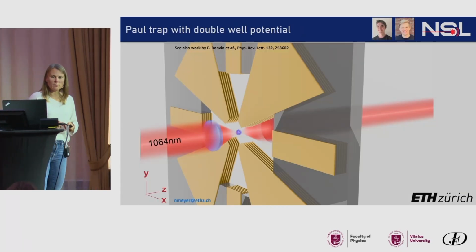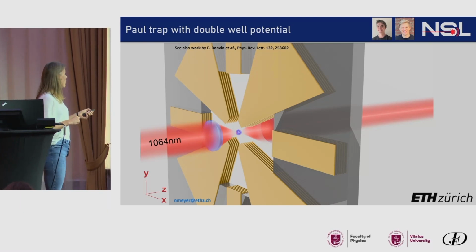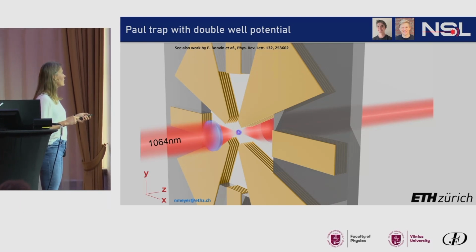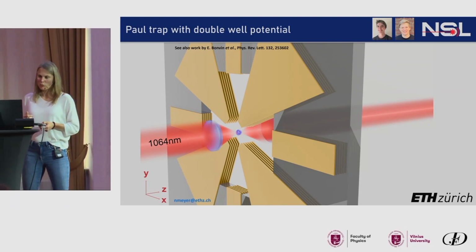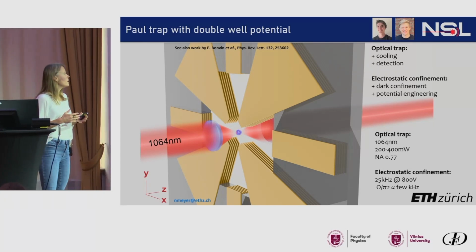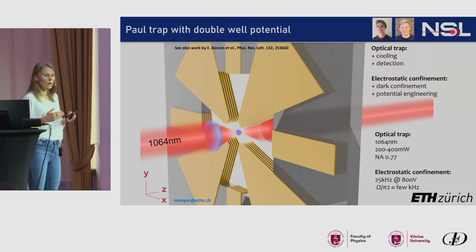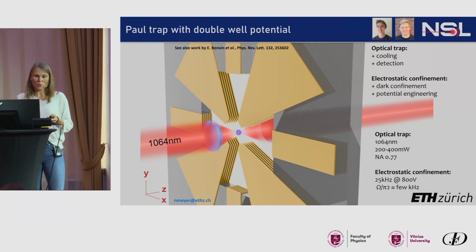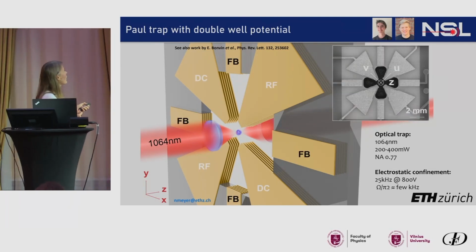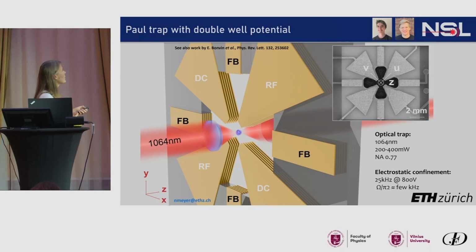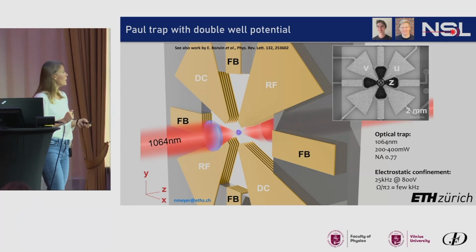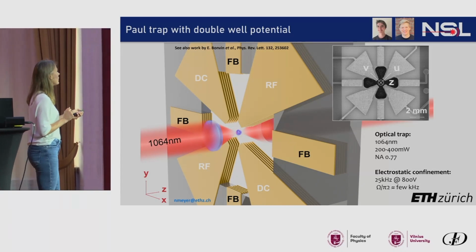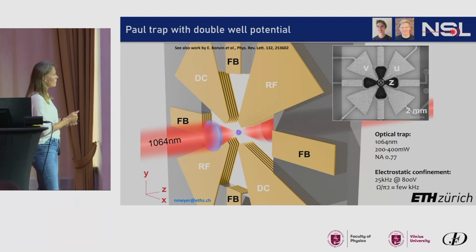The platform itself looks like this, where we now have an optical trap that catches the particle, and around it we have a chip that accommodates a certain set of electrodes, and there are basically 3 tasks that this chip needs to do. So on one hand, it needs to provide a Paul trap, which is these 4 electrodes here. Maybe you can see them better in this picture here, which are now 45-degree rotated in comparison to the optical axis of our detection, basically.